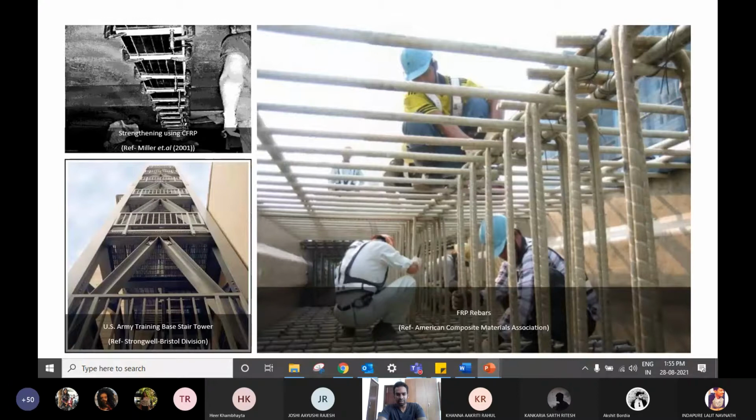Okay, and that's why they use FRP rebars in bridge applications. So FRP rebars are kind of used where bridge girders or bridge decks are being built, because your bridge is mostly over a water crossing, right? And it has its environment effect, which could be susceptible for corrosion. So in order to save it, we kind of prefer FRP rebars. And there are some other design parameters we need to look at before we finalize. So that's one of the applications.